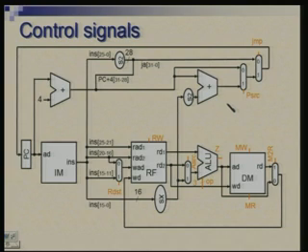So, we require some circuit which will produce so many outputs. So, 1, 2, 3 plus 3 6, 7, 8, 9, 10, 11. These 11 outputs, and that control will have to look at this and also look at two fields of the instruction, the opcode field and the function field.